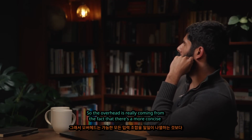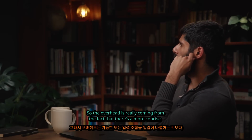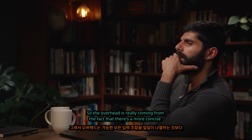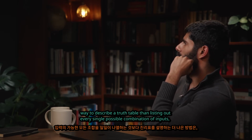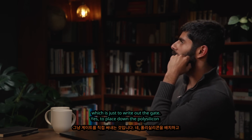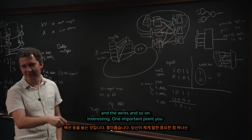Right. And so the overhead is really coming from the fact that the mux in the lookup table is a more concise way to describe a truth table than listing out every single possible combination of inputs, which is just to write out the gate. Yeah, like to place down the polysilicon and the wires and so on.